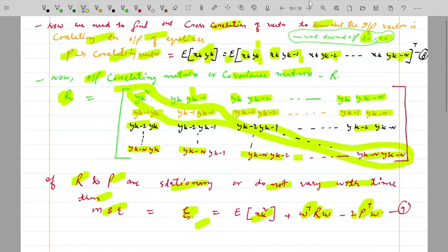This is because when the input signal y of k and the desired response, or estimated response d cap of k equal to x of k, are stationary, the mean square error is quadratic in the weights W of k vector. Minimizing the mean square error leads to the optimal solution for the weights. So we want the output of the equalizer to have minimum mean square error.